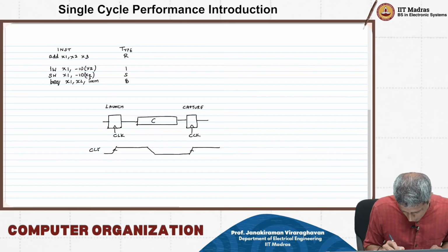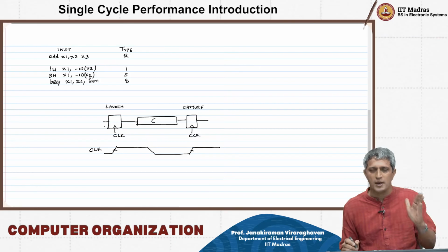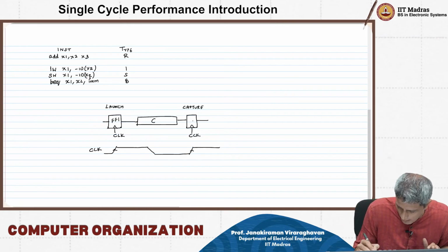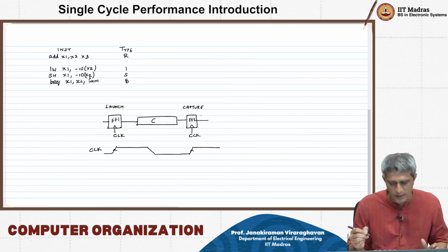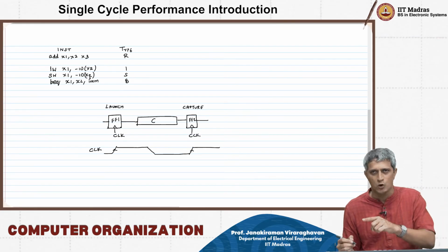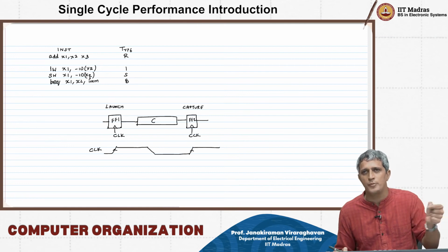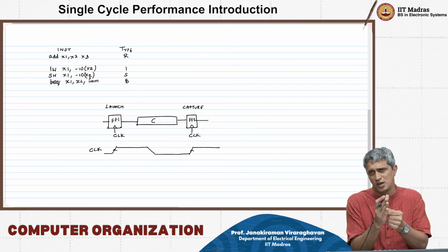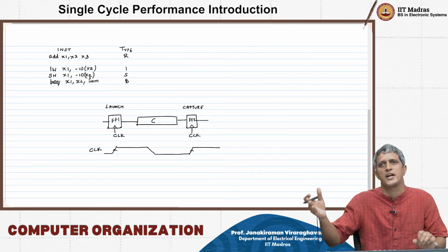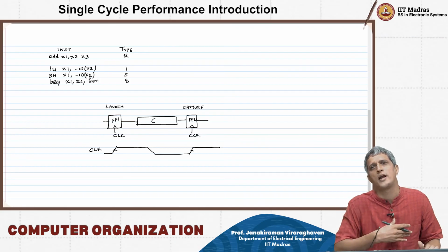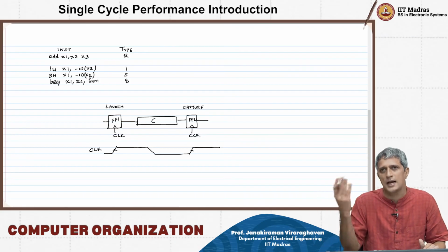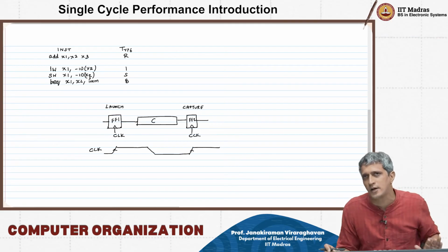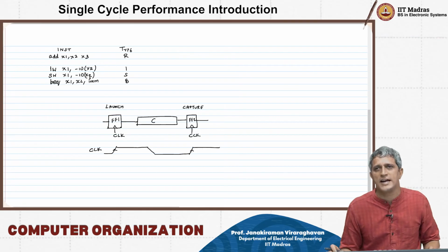If you look at the clock here, you have some data coming in ready for the flip-flop FF1 to launch. On the positive edge of the clock, that data goes through. Then it's a combinational block. That means once the input is presented to the combinational block, after a finite propagation delay, you are going to get that output changing at the output of the combinational block, and that needs to be captured at the next rising edge appropriately.